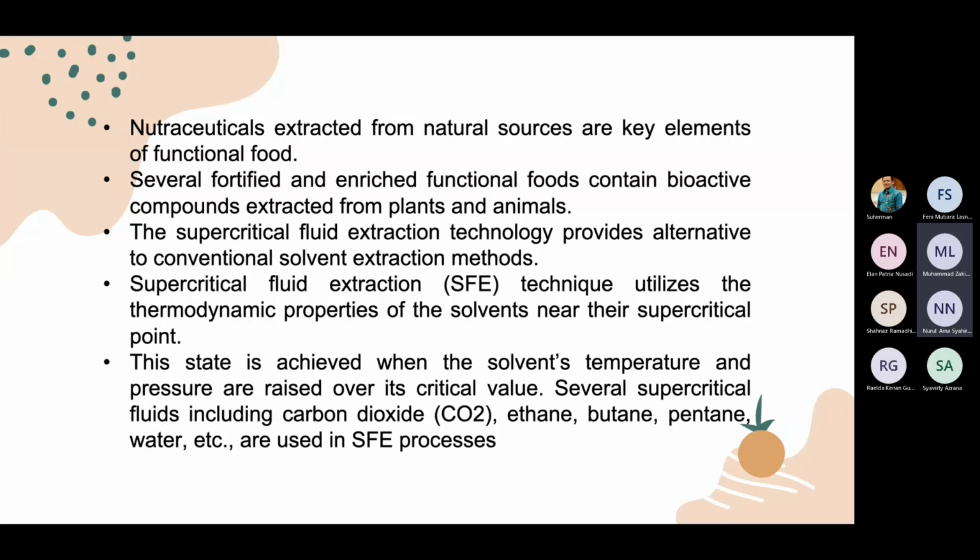SFE technique also utilizes the thermodynamic properties of the solvents near the supercritical point. This state is achieved when the solvent's temperature and pressure are raised over its critical value, or we can call it supercritical. Several supercritical fluids, including carbon dioxide, ethane, butane, pentane, water, etc., are used in these SFE processes.